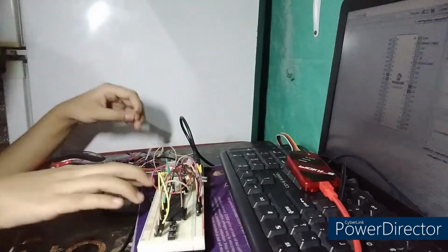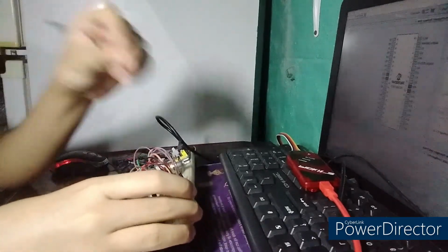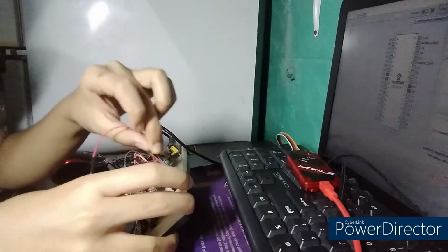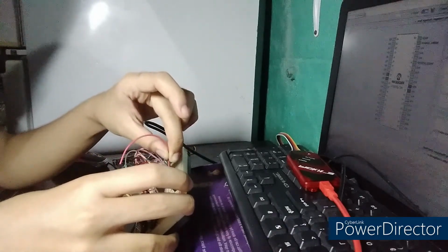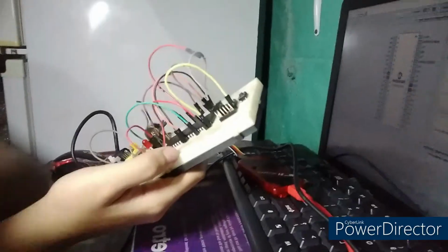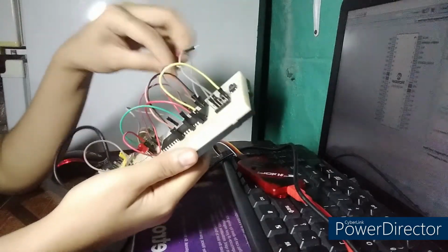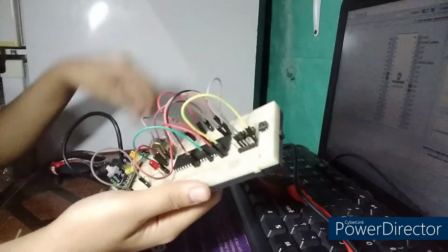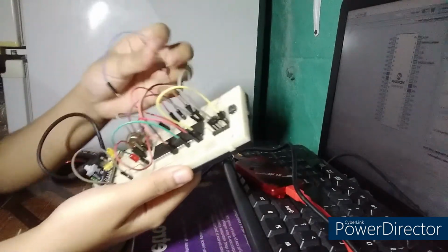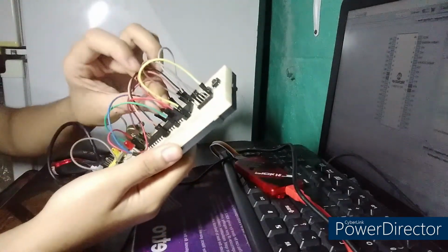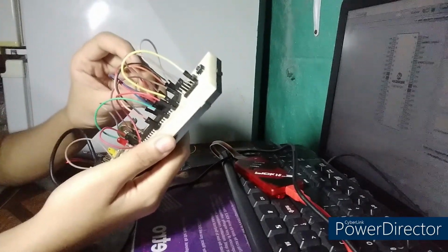And then on the other side, let's connect the VDD again. It's on the 32nd slot pin. So 40, 39, 38, 37, 36, 35, 34. So on the 32nd pin, VDD should be connected to our positive terminal. And then let's find a gray wire here. Our VSS is connected to our ground, which is on the 31st pin of our IC.